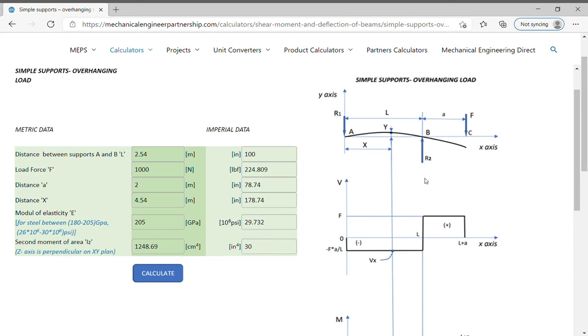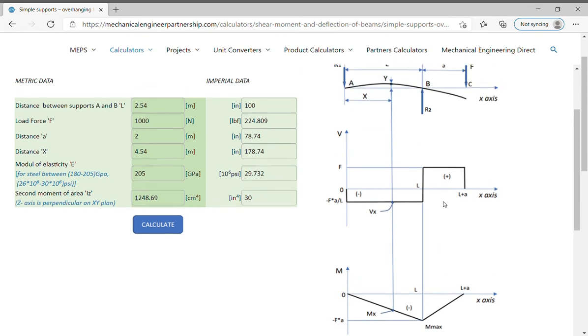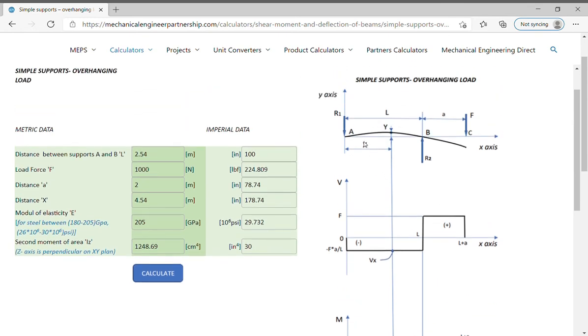The shear force is obtained by summing the forces on the isolated section. The bending moment is the sum of the moments of the forces to the left of the section taken about an axis through the isolated section. The sign conventions used for bending moment and shear forces are, clockwise for positive moments and counterclockwise for negative moments. Positive shear forces are in the same direction as the y-axis in the figure and negative shear forces for opposite orientation.